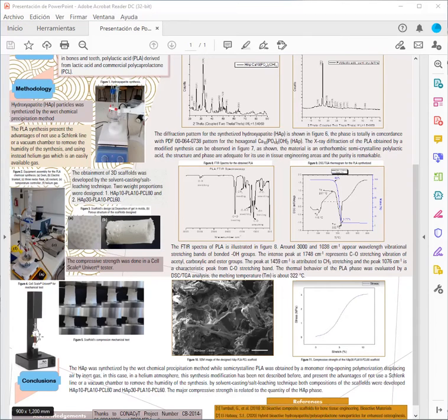Cancellous bone plays an important role as a primary load-carrying component that absorbs energy. This bone is an anisotropic and porous composite, and its mechanical properties depend not only on the porosity, but also on the arrangement of each trabecula, and it has a modulus of about 0.5 gigapascals.